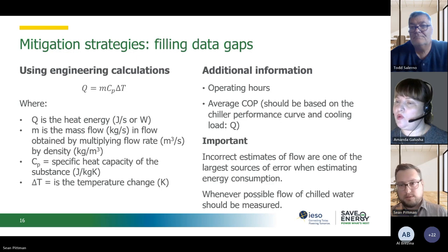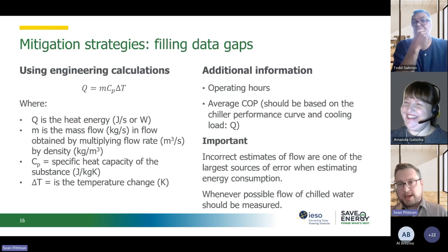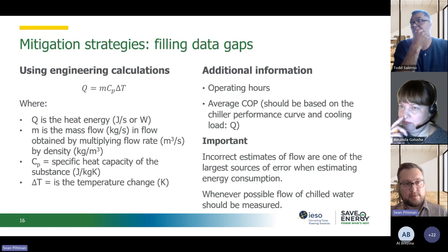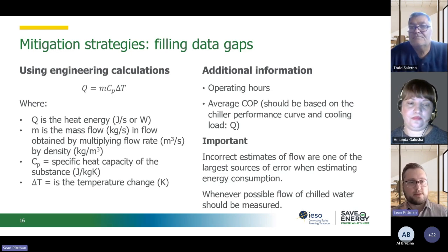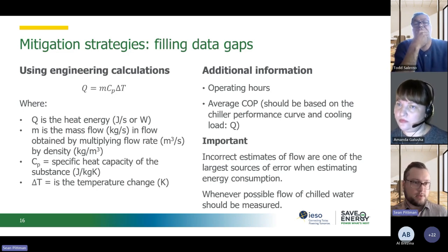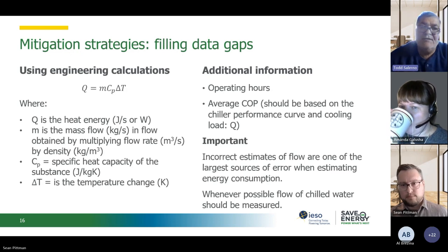Okay. And what about the accuracy of that, I guess? Yeah, anytime you're using a meter, you have to incorporate the accuracy of that meter within your calculations, and so you need to follow through to calculating your project savings uncertainty to understand whether that amount of uncertainty is acceptable for the outcome you're looking for. So, yeah, go ahead, Todd. Yeah, from my experience, I've used the clamp-ons, the ultrasonic meters.